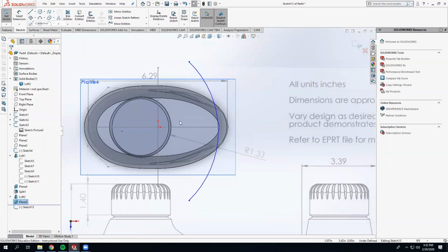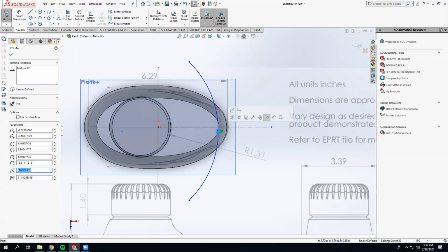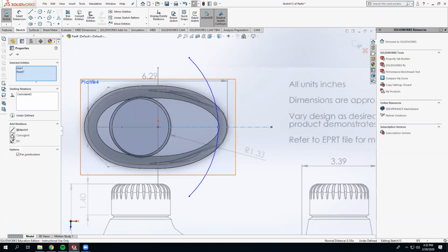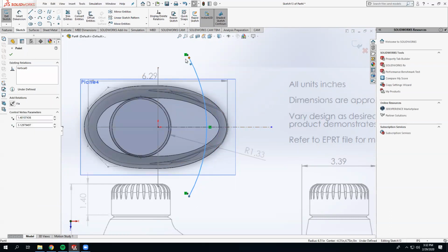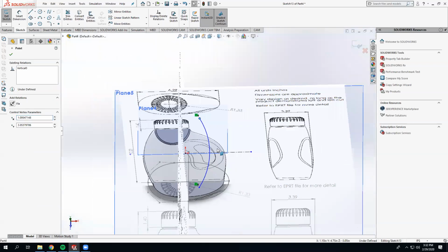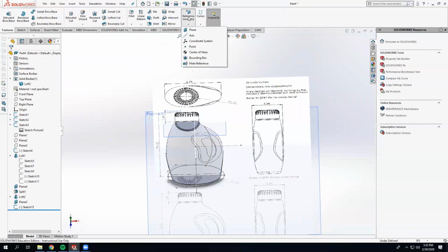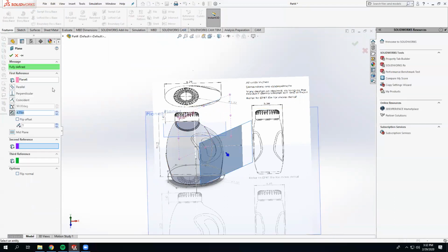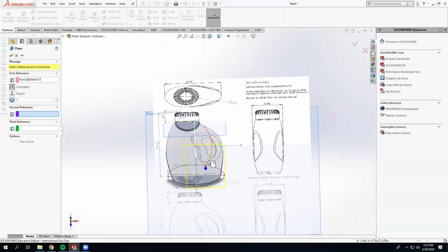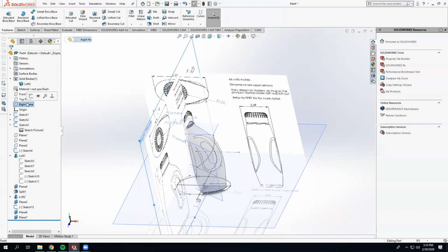And then I might need to have a center line here and take this and do, I'm looking for this point, which is the midpoint of the arc, and then coincident. So now it's just there. Yeah, and that should be okay with that, I think. So that's gonna be how I'm gonna create those planes there. I will do plane, point, plane, point. I will go to my right plane so I can sketch that shape.